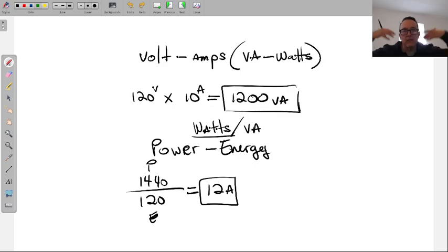So we get so wrapped up around wattage, we got to break that understanding as electricians. That microwave is actually 1,000 VA. Watts would be the microwave actually turned on and in use. Now, why is that different? Because of the 120. Measure your outlet. Do you have 120 that you've plugged that microwave in? Are you sure?